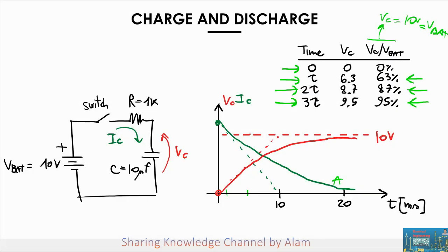In this circuit, the time constant is equal to RC. So it makes sense that it depends on both the resistor and the capacitor. After all, this circuit is very simple, and these two are the only two components we have. But I want to give you an intuitive understanding of why the product of those makes sense, rather than, let's say, the ratio or the difference or even just one of them.